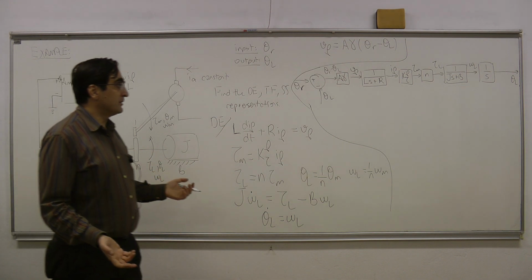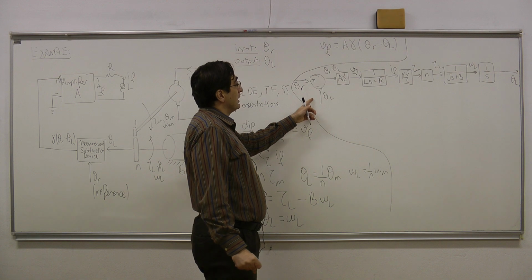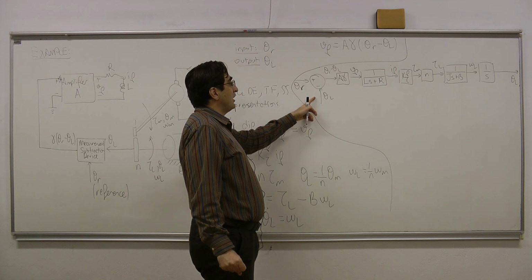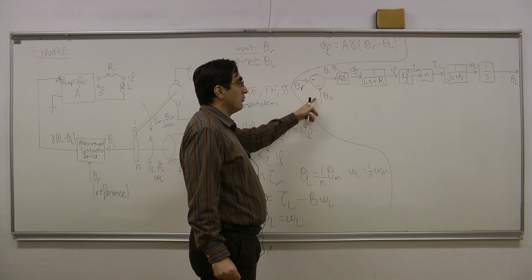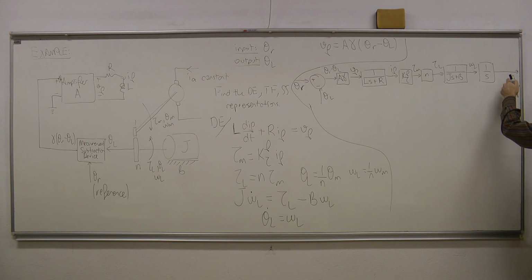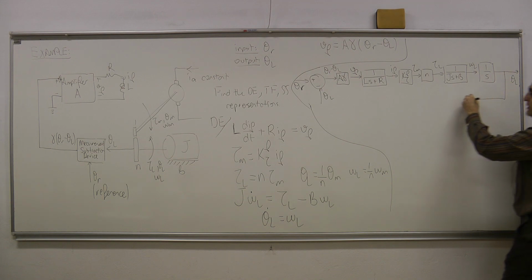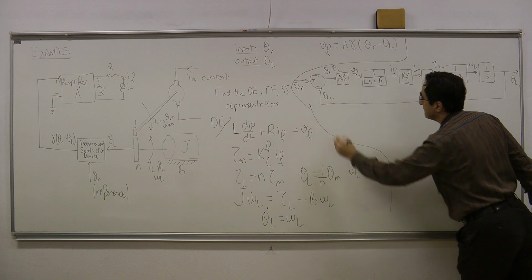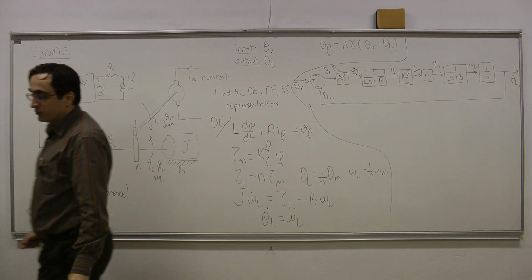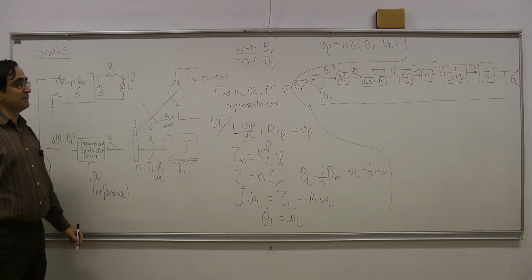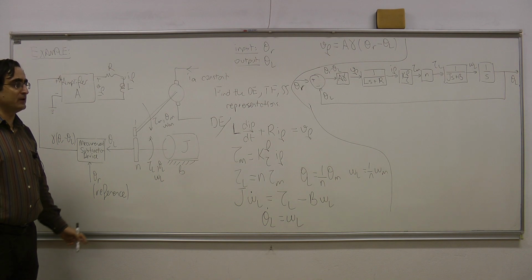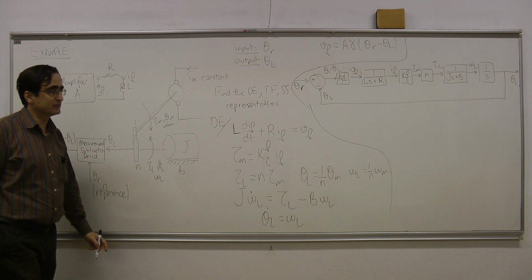Okay? The only thing missing here is this missing variable that I did not connect anywhere. So this is my subtraction variable theta L, which is the output, and theta L is here at the end of the block diagram. So what I'm going to do is just connect this theta L into the feedback path. So this actually completes my block diagram representation, and now by using this block diagram I can find the overall transfer function of the system.